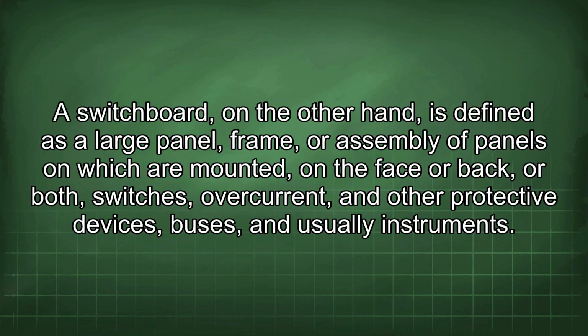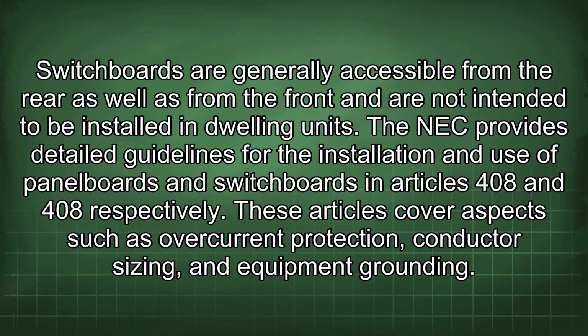A switchboard, on the other hand, is defined as a large panel, frame, or assembly of panels on which are mounted, on the face or back, or both, switches, overcurrent, and other protective devices, buses, and usually instruments. Switchboards are generally accessible from the rear as well as from the front and are not intended to be installed in dwelling units.